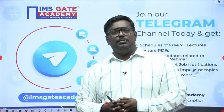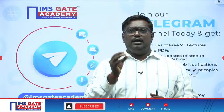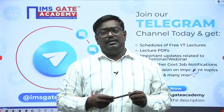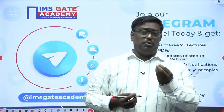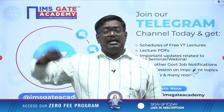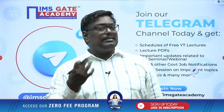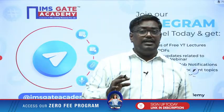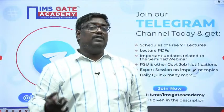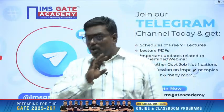Now let me tell you, my dear students, if you are really preparing for geotechnical engineering, very important things, like the critical hydraulic gradient. This is also one of the important concepts in quicksand. If in quicksand condition the upward seepage pressure becomes equal to the submerged weight, in this case the sand loses all its shear strength. Most people will think that quicksand is a type of sand. Let me tell you, it is not a type of sand.